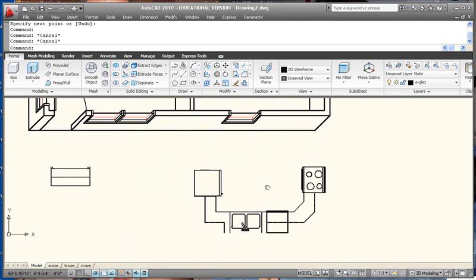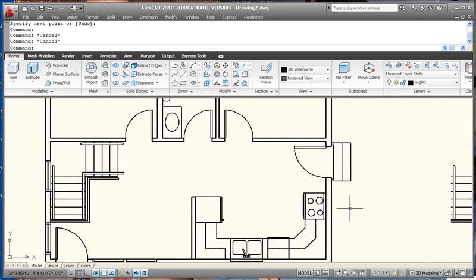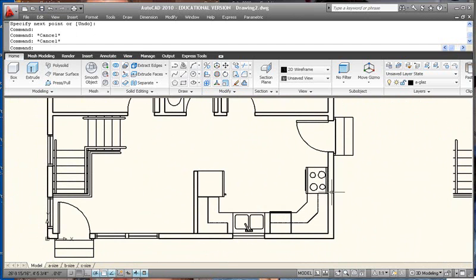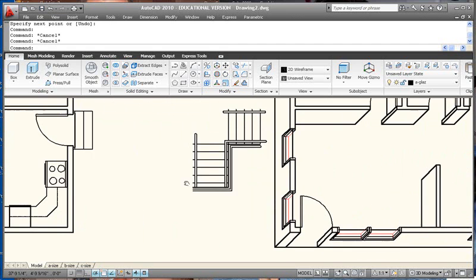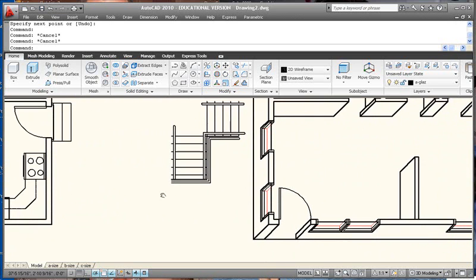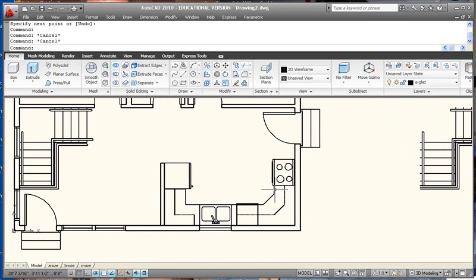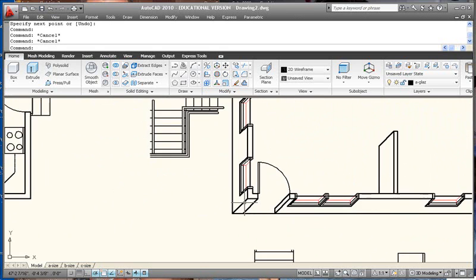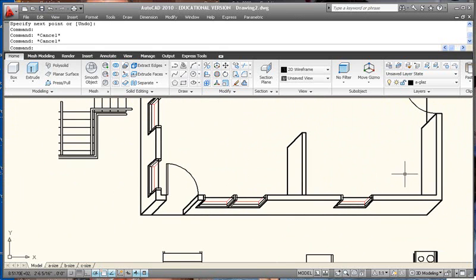Now the kitchen, what we had going on in the kitchen here, let's go back to this plan here that's just showing it in a two-dimensional format, is we have some countertops. And countertops are generally 2 feet tall. And remember, everything that's representing height in this plan over here needs to be divided in half so that we draw it correctly over here. So anything that would be 2 feet tall here, we'd use a line that's 1 foot long here to represent that.